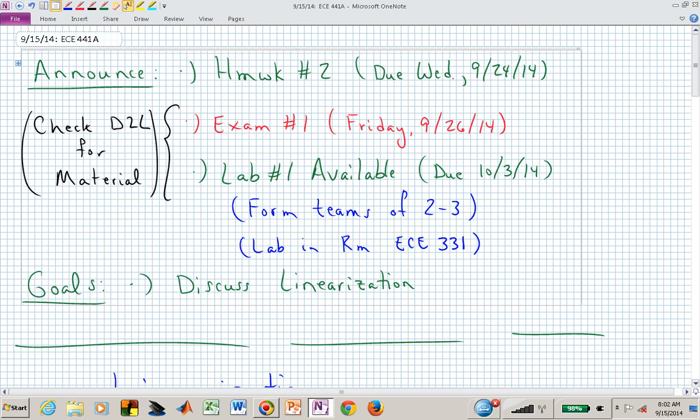And you will also attach your particular spring, and then you will try to identify what the spring constant is, what the damping constant is, and from that you'll have your transfer function for a second order system. That's lab number 1.